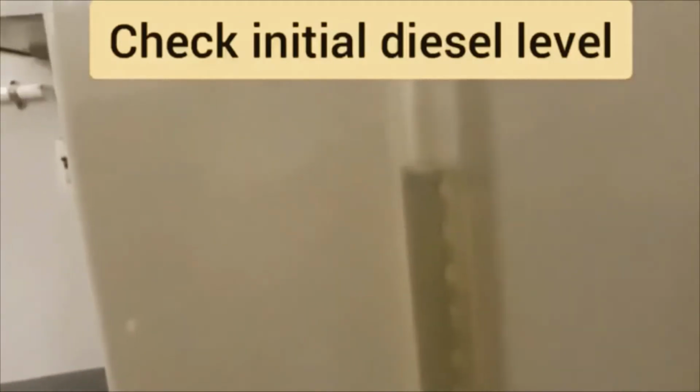Now here you can check the initial diesel level before starting the engine. Here you have the initial mark for starting the engine and the second mark for stopping the engine. So we calculate the total fuel consumption during the running period of the IC engine. For the fuel consumption, we have taken the mark of 10 ml.